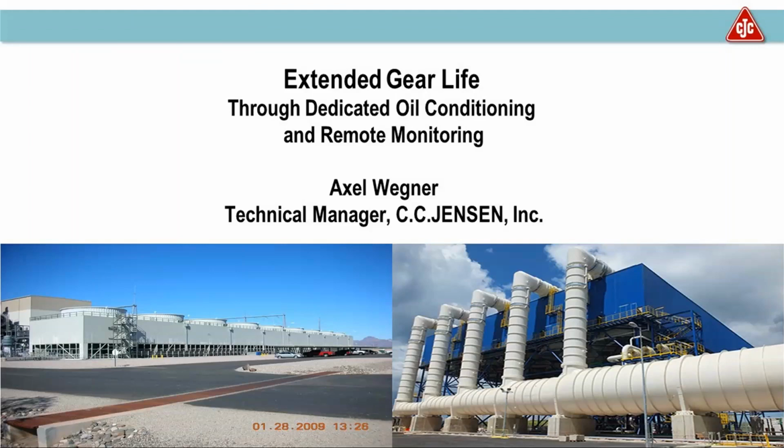No, we don't. And there is one main reason for that. If you're trying to valve several gearboxes to the inlet and outlet of the filter, you actually have a chance of drawing one dry and overfilling another if the valves are not operated properly. And I do understand that it is, of course, a cost factor if you want to put one filter on each gearbox.